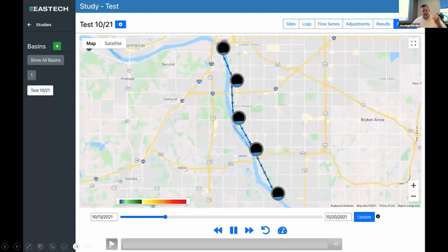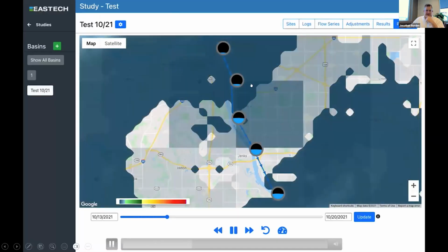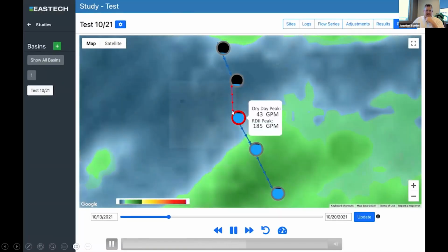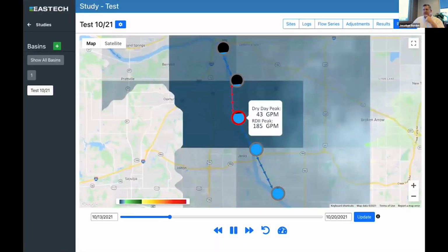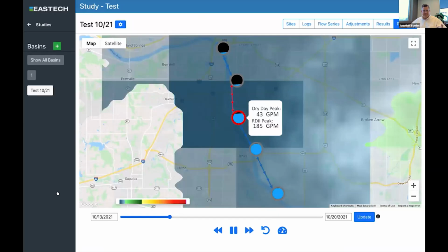When it all comes up at the end of the day, this is what our final output looks like. You can see the weather flowing across a network of sensors. You can see the water lifting up in those sensors and highlighting this middle one as where the I&I is coming from. It's pretty amazing capabilities now. Once again, the key is that we're putting these sensors into a network to talk to each other and then overlaying them with the weather.